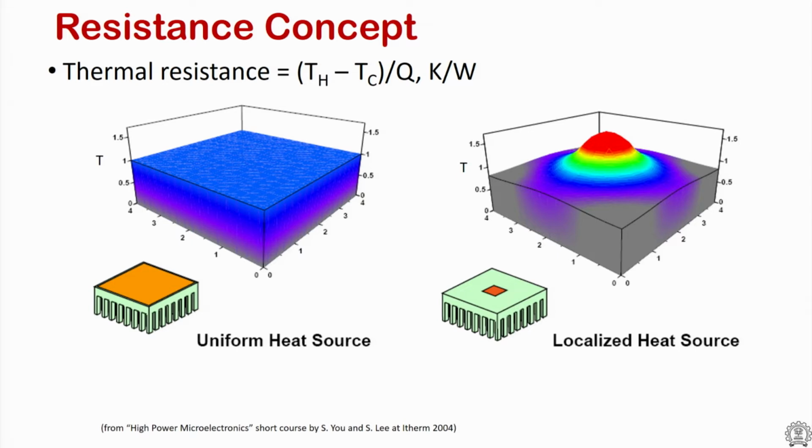While the industry wants maximum temperature, thermodynamically we cannot define a resistance based on a point temperature and an ambient, which is a larger reservoir. A thermal resistance is often defined between two reservoirs that are maintained at isothermal temperatures.